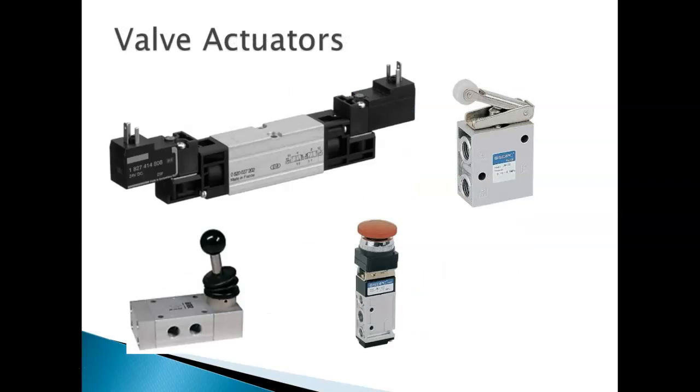So, some different valve actuators. This guy again is your solenoid. You can't really see what it's doing, but you can see where you tie the electricity into it. You've got your roller valve. That's a very common one. You have a lever and you have a push button on this one. All those are doing is creating different ways to move that actuator so that you can change what it's doing.